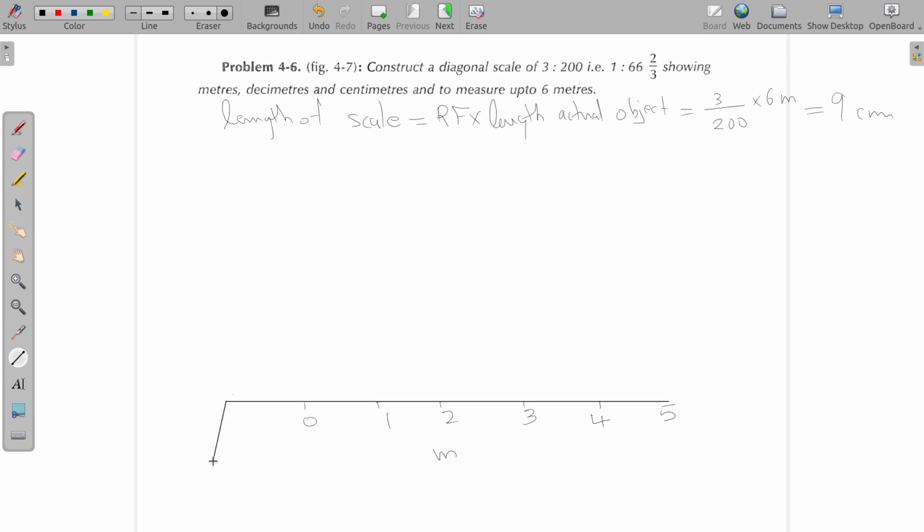Let's say I'm going to draw a line. I'm simply drawing it here so that we can use the top part for some other purpose. So we would like to divide this into 10 parts. Divide into 10 parts and connect this end of the line to this end and draw parallel lines from each of these points. Draw a parallel line from here, here, here, and from all these points you can draw parallel lines.